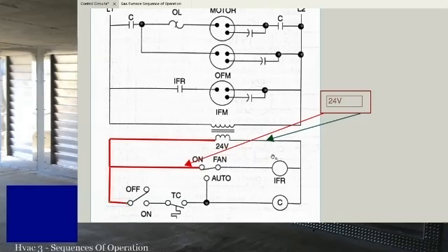But as you're troubleshooting these components, right? Say we've got an issue where the fan isn't coming on, and you're trying to check it at the relay. All right. Do not troubleshoot to ground on your low voltage side unless your low voltage transformer is grounded. And if you're not sure, just assume it's not. You can troubleshoot to ground if your low voltage transformer is grounded to the chassis, but a lot of times, especially if it's 24 volts, it won't be.